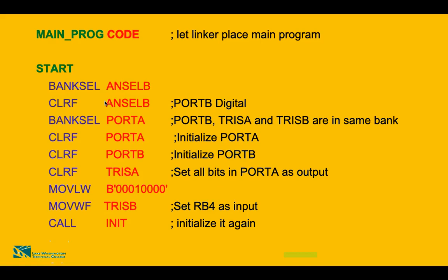So using BANKSEL we have selected TRISB, and we are clearing all the bits of TRISB, and making this PORTB a digital input.